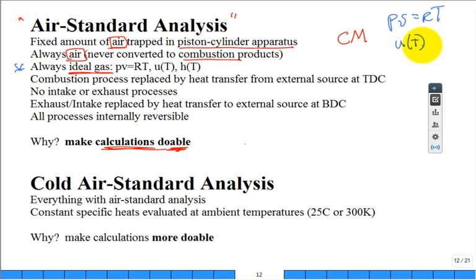That's a lot different than what we had for steam. Superheated steam, if I want to know the internal energy of superheated steam, I need to know temperature and pressure. Do I need to know pressure for the internal energy of air behaving as an ideal gas? No, you do not. All you need to know is temperature. That you need to think about. If you haven't already struggled with that out of Thermo 1, struggle with it now, because I get a lot of questions and it goes back to that fact right there.